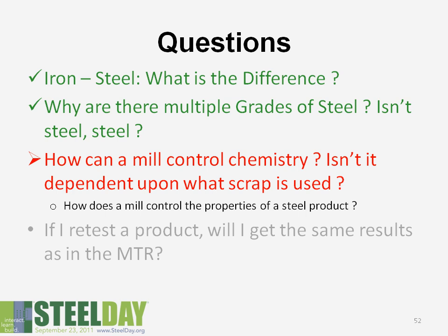There are some processing things, which we'll see a little bit later on, that things like angles may be too light, that you're getting too much strength in them, that you can't get the alloys or the carbon levels down low enough to actually meet the A992.